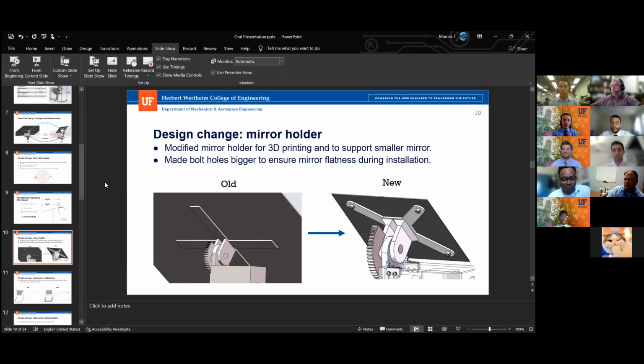So I feel tension might be a bad word to use, because I was going to clarify, it's not in high tension. It's just with a little bit of wiggle room, we were able to pull the bolts apart enough that it would eliminate any sort of buckling and allow for the flatness. Because with proper tools and better manufacturing, you could probably drill exact holes into the acrylic mirror. But with the drills that we had, and the possibility of cracking it, we came up with a quick solution for the prototype to just make sure that we could pull it tight and flat.